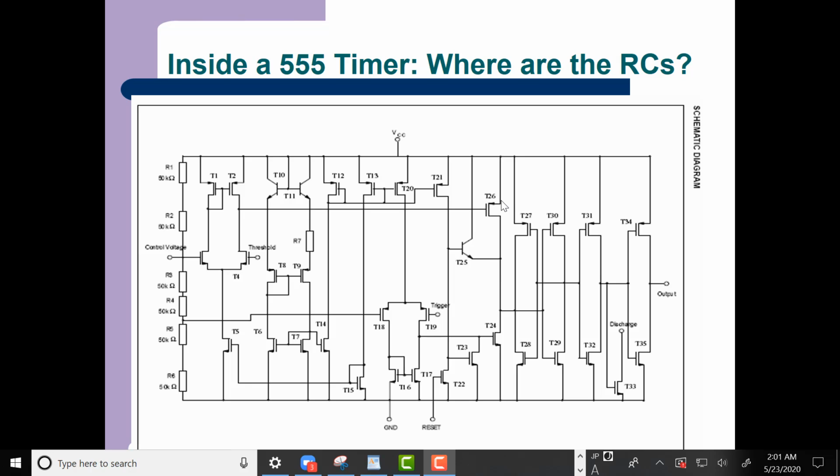And what happens is when you have a stage, you change the input to that stage. If it's a common emitter, you change V in, and then the output of that stage, V out, would change. Okay. And when you're changing the voltage at a node, looking at the output of the stage, what you're doing is you're charging up or discharging capacitance.